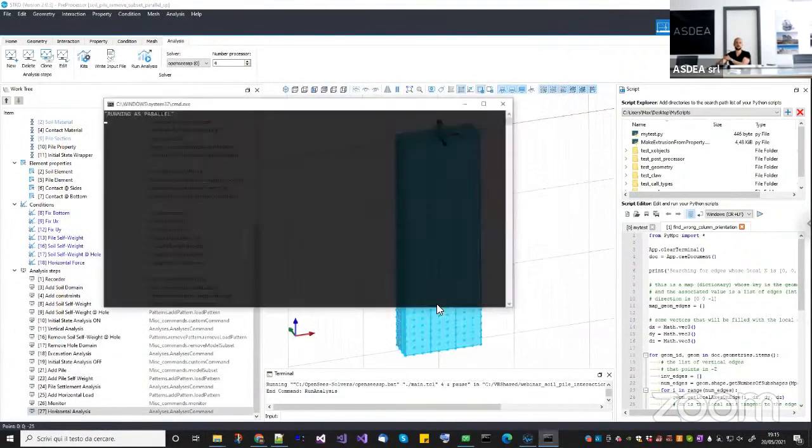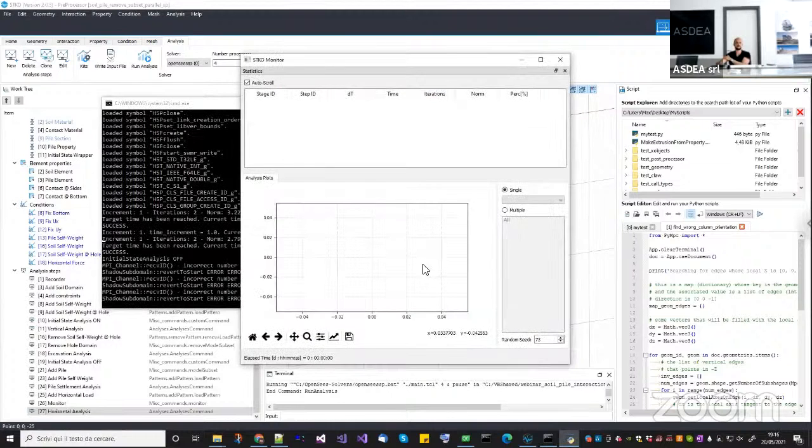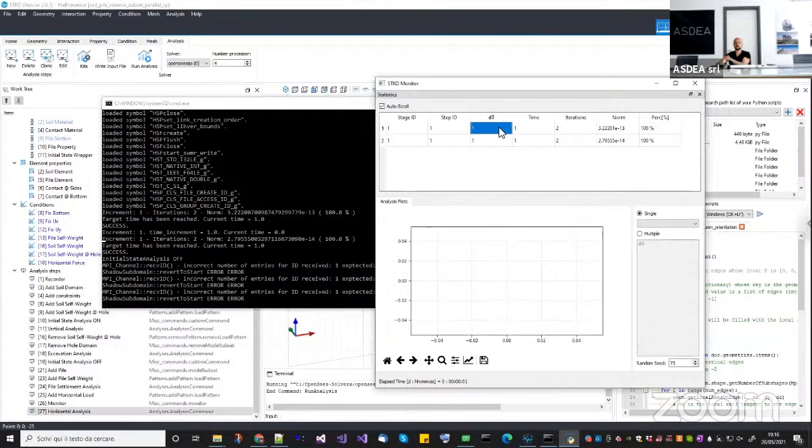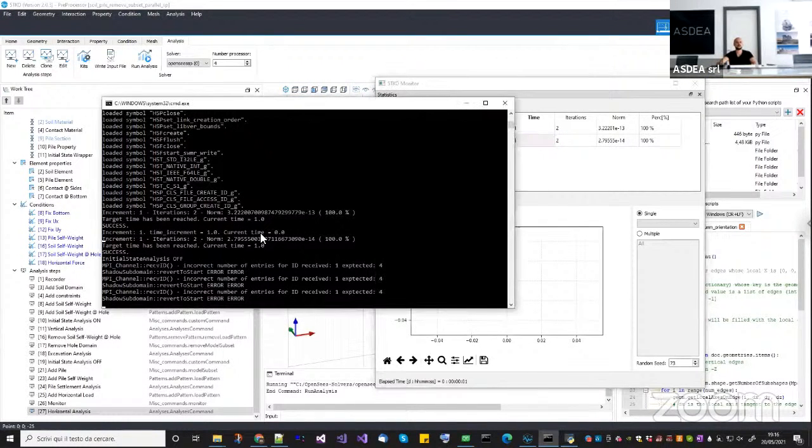You will now see the error that will happen with OpenSees. The first analysis is fine, which is the vertical analysis, then the hole, so we perform the excavation analysis. Then I put the beam and the contact elements, and here you will see an error about the MPI channel. This is basically an error inside the contact element, which is not able to communicate between one process and the other.